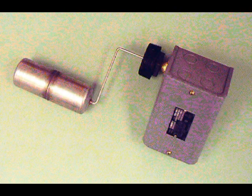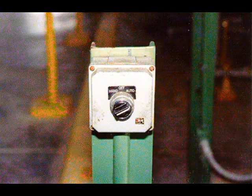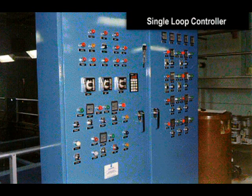However, they can be troublesome in systems with high grease content. Simple systems using floats generally require very little in the way of control strategy. Some way to switch between hand, auto, and off settings is usually all that is necessary. The more complex the control device, the more complex the control strategy. One type of control strategy is single and multi-loop control, a combination of instruments or control functions that are arranged so that signals pass through each device or function for measurement and control of the process variable.